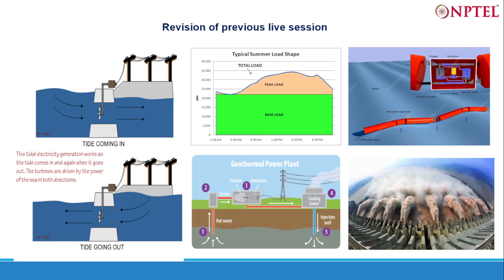So one thing you have to remember, energy capacity is 1325. That doesn't mean it will always produce 1325. It has the capacity to produce 1325, but it will always produce somewhat less than that. So we have a term, capacity factor. The capacity factor tells us the ratio of actual electricity generation to how much it can produce at maximum. Okay, so there is a term called capacity factor.